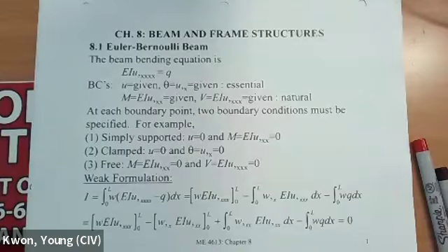You guys took statics at some point, right? So a truss structure is the simplest structure, which only what? Consists of two-force members. Two-force member means that member is going to carry the load along the member direction, no bending.